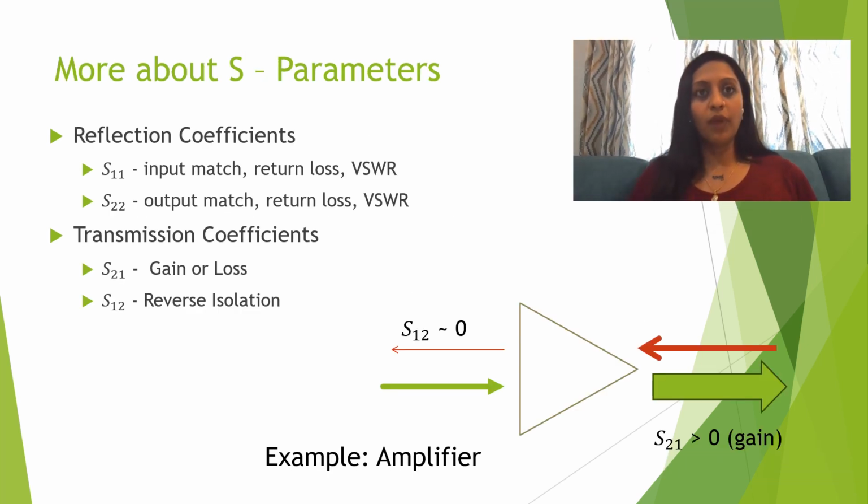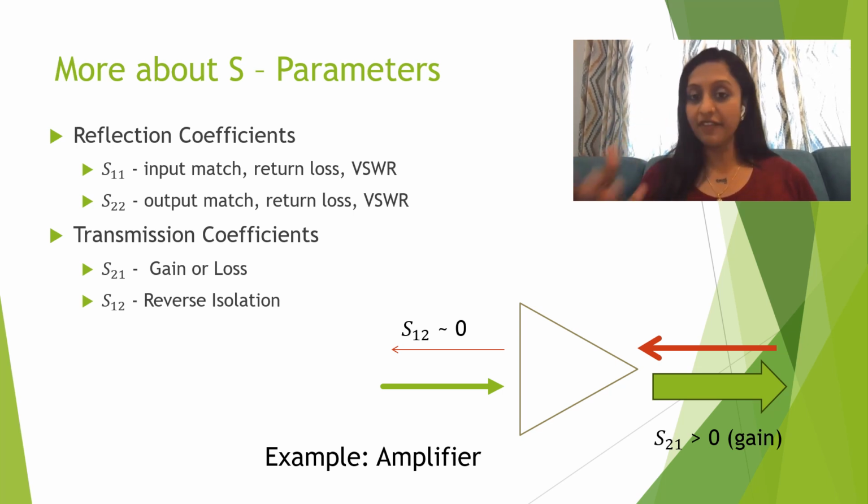Well, having known how to analyze a 2-port network in terms of S parameters, either in terms of any combination of these four, S11, S12, S21 and S22, what does it give me? I can relate it to either reflection coefficients or transmission coefficients. Reflection coefficients relate only the same subscripts for input and output: S11, S22. So what does it say? This says the input match.